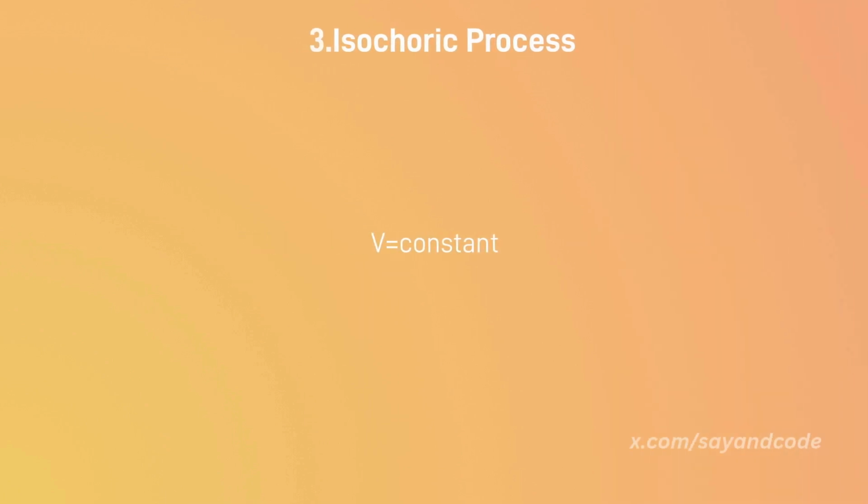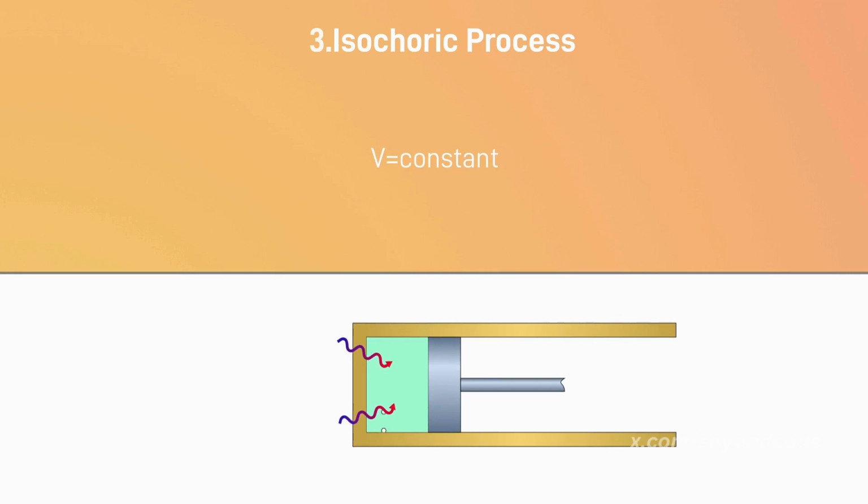Another example, commonly used in thermodynamics questions, is heating a fluid inside a piston cylinder, where the piston is restricted from moving, or is fixed. Since the piston is fixed, the volume remains constant. But the temperature and pressure increase because of the heating of fluid.